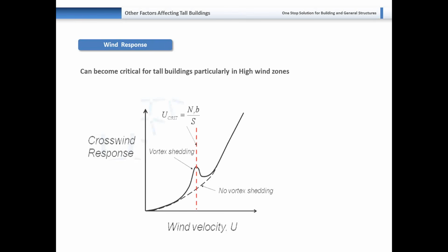Additionally, the wind effect in tall buildings is almost always investigated using wind tunnel testing. This not only helps us gauge the wind effect on the structure, but also helps us find the optimal cross-section for different floors. For example, when we go for a building design and do a wind tunnel response, we normally do it for several different types of cross-section.